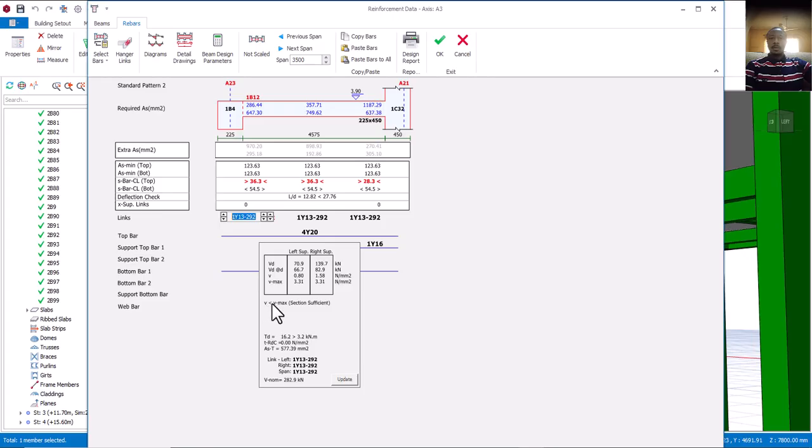your shear is less than the maximum shear. Is that okay? This V maximum is the maximum shear strength of your beam, while this V is the load on your beam, the shear presently on your beam. Looking at the strength of that beam, this is the maximum capacity, my maximum shear strength. And the shear on the beam is less than the maximum shear that this beam has. That's why it has passed.